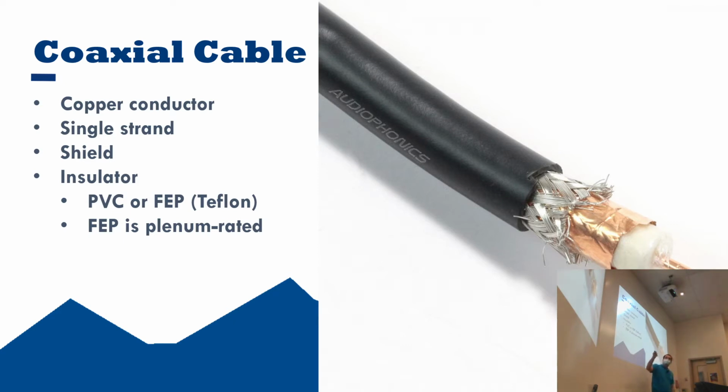So Teflon is going to really mitigate a lot of those problems. And it's going to allow us to run cables through a fire barrier as long as we make sure to insulate well with fire-rated compound around the cable through the penetration in the wall or ceiling or wherever. It's not going to allow fire to pass through it.